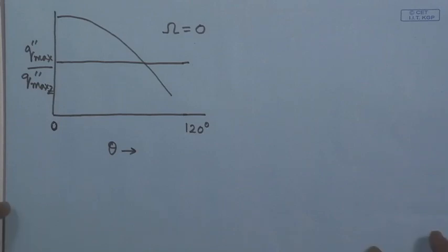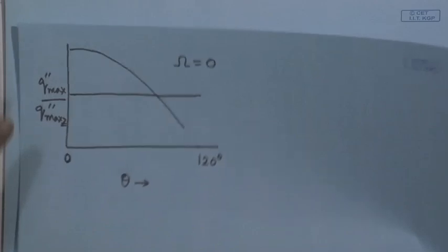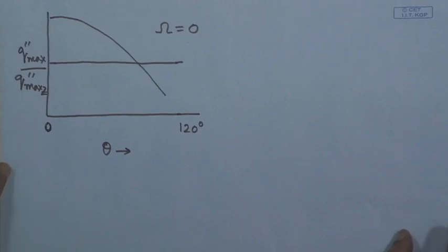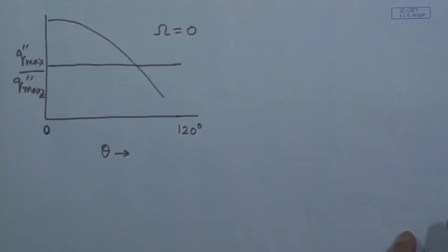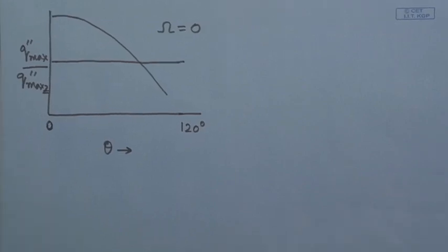So, you see that for critical heat flux we have got some hydrodynamic theory which has got other limitations, but critical heat flux is quite a complex phenomenon. So, with this theory at least certain aspects of it we can explain, and it has got reasonably good success in predicting the experimental data. But there are again some discrepancies.